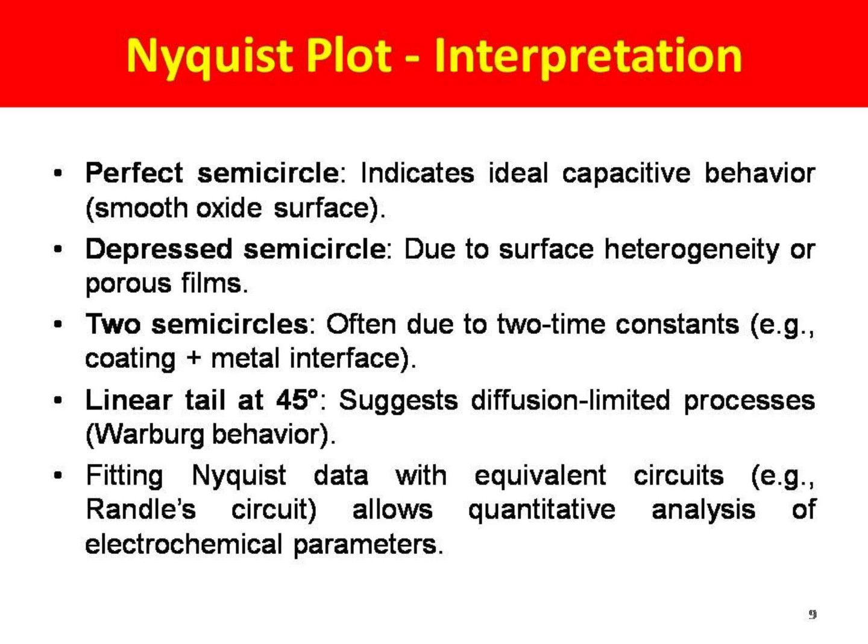If you obtain two semicircles, it is often due to two time constants, and a linear tail at 45 degrees suggests a diffusion limited process, that is Warburg behavior. Curve fitting the Nyquist data with an equivalent circuit allows quantitative analysis of electrochemical impedance.